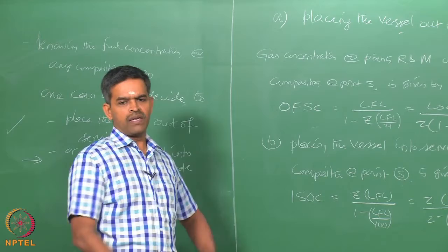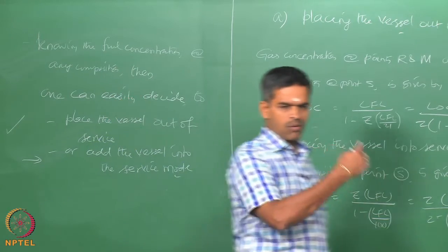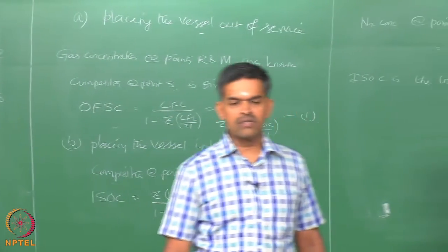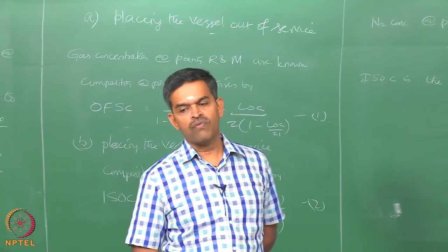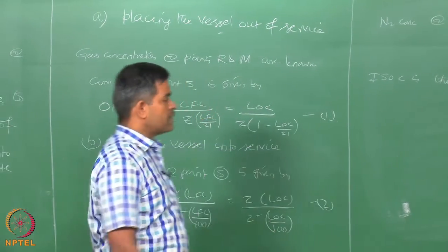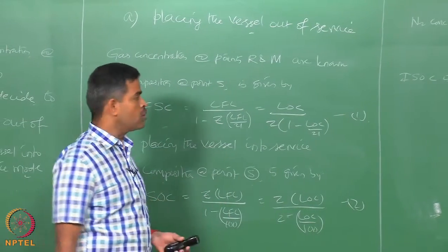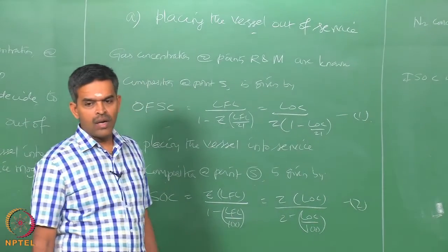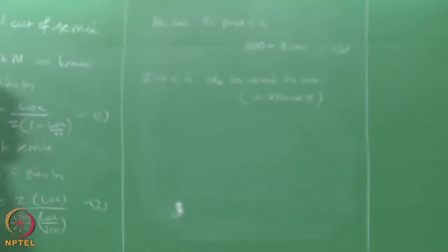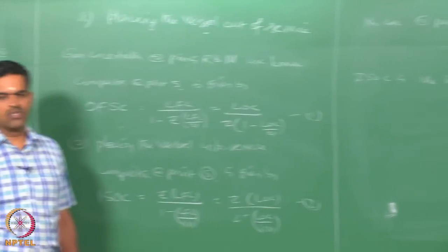The first set were inerting and purging, for which we explained about 6 methods. We also said what the required nitrogen concentration or oxygen mole fraction would be to do the inerting and purging operation. In the second set of discussions, we discussed the use of the flammability diagram and knowing the concentration of nitrogen as well as oxygen in service or out of service from the equations given to you on the blackboard.